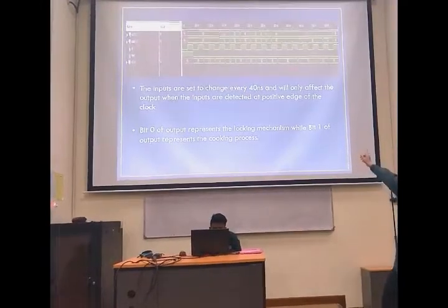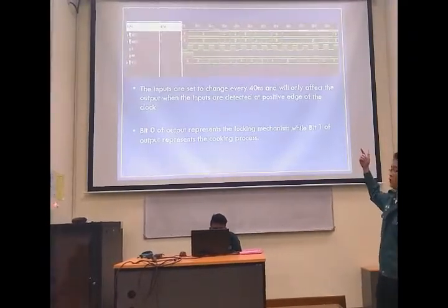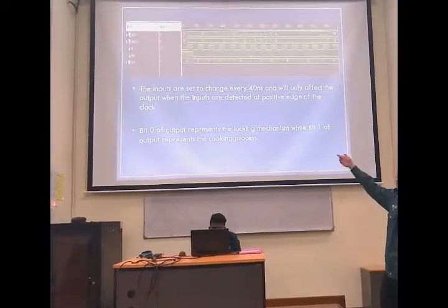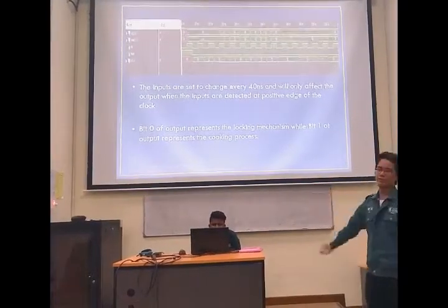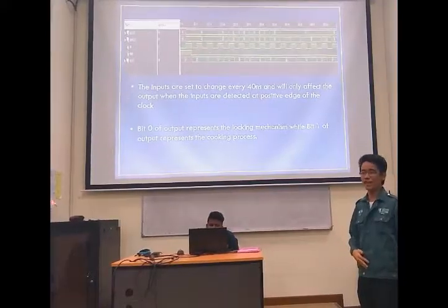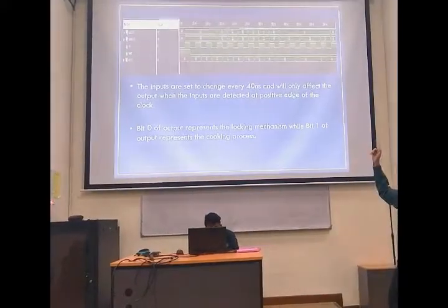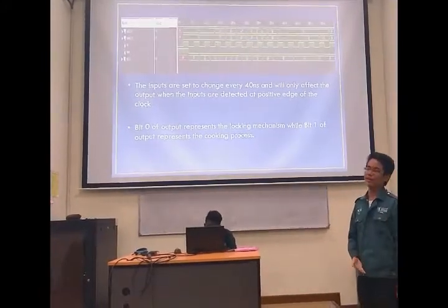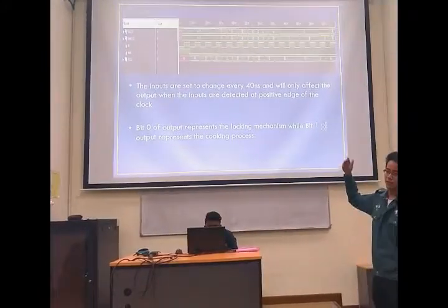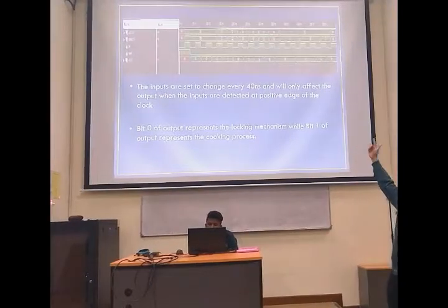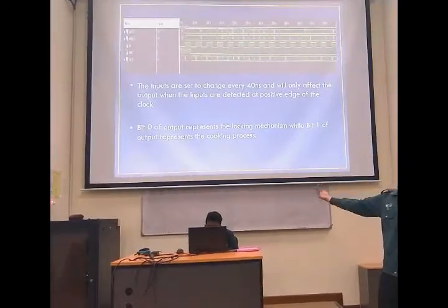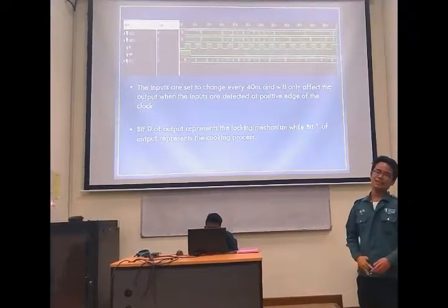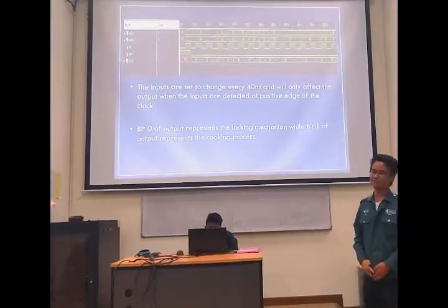After that, we go into the cooking state, which is the input bits 1, 1. This also shows that our state is now 1, 1, which is the 4th state, which means it's cooking, and our output is 1, 1 as well, which means that the locking mechanism is on and the cooking has already begun. So from the first 5 inputs that I just showed, we can assume that our simulation is correct and it's doing exactly what we did for the state diagram.